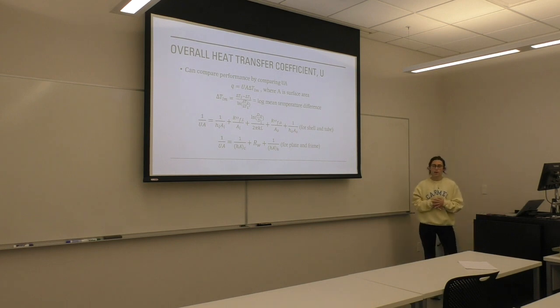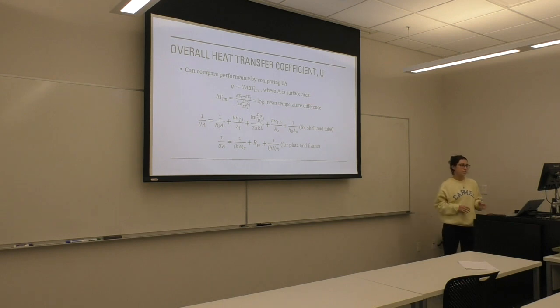As far as comparing heat exchangers to each other, there are heat exchanger efficiency equations. In heat transfer, we learned about the NTU method, but those are super extensive and complex, and again, depend on what type of heat exchanger you're looking at. But if you wanted to make a general comparison just between two, you could calculate the overall heat transfer coefficient for the heat exchanger, as well as the total surface area that heat transfer is occurring across, to compare the performance of two heat exchangers.